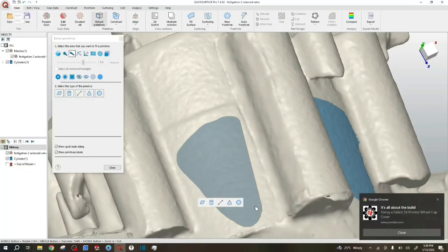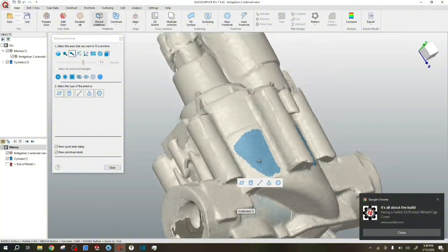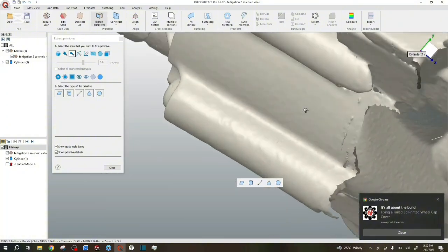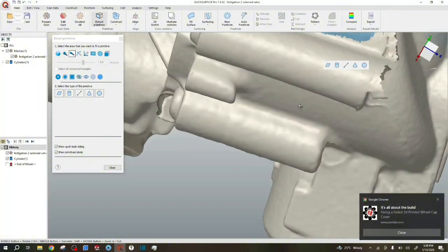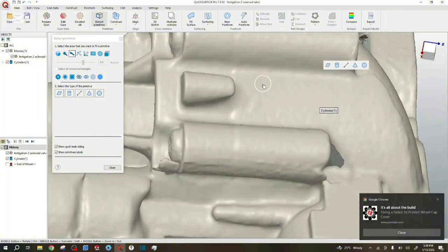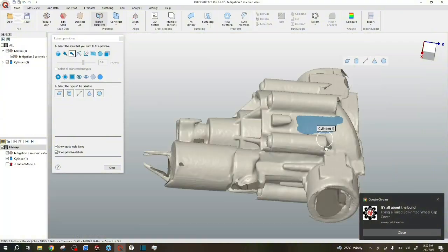You don't want it to affect our selection so much. That part to the other side, click on section like so. Quick Surface has such a nice feature where it just sticks on the mesh, so everything just snaps on the mesh like so.